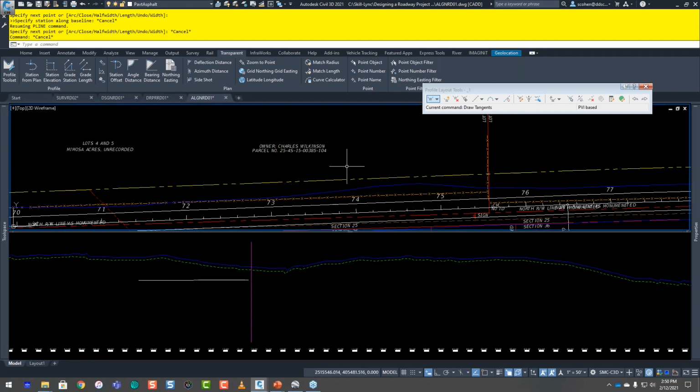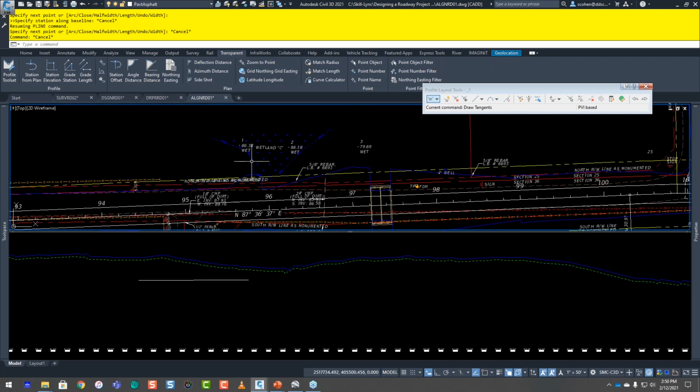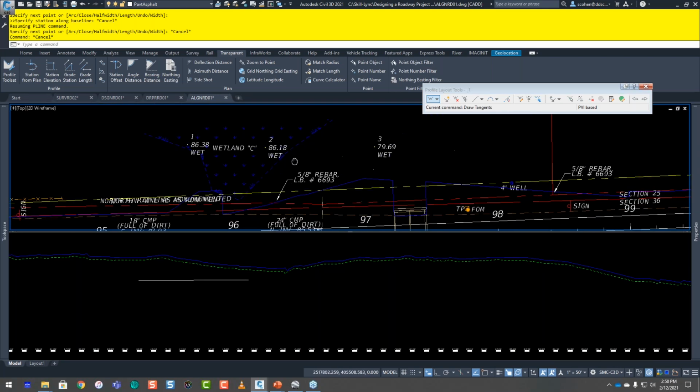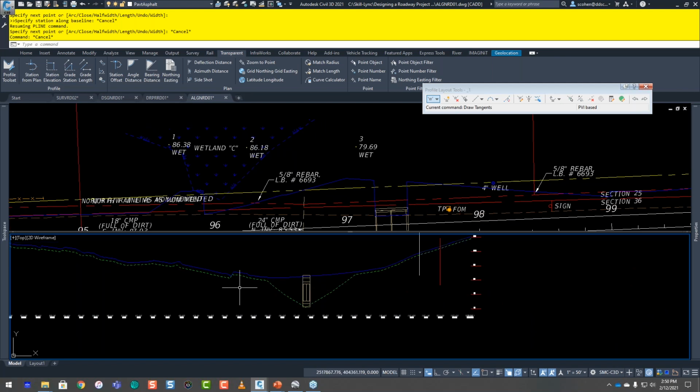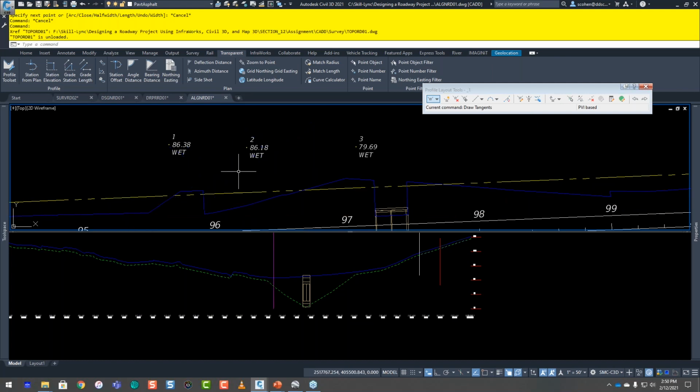Now, let's say I have some COGO points already in my drawing, and I want to project them in here. I want to see where that is in here, so I can actually know where my wetlands are, or let's say you want to go below a pipe. You've got an invert somewhere, and you want to make sure you're defining your low in there. So what you can do, a little tip, first of all, the way this command works is it's a little bit hokey. I'm going to right click and I'm going to unload my reference file. It'll make it easier.